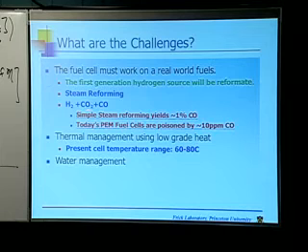You're supposed to only generate CO2, which is an issue in and of itself if you think that fuel cells are the answer to greenhouse gases. But you could think about things like you're going to do this in a big factory and you're going to collect the CO2 and stick it in California because you live in New Jersey or something like that. The real problem is you generate quite a bit of CO. In a typical one-step reforming reaction, you generate 1% CO in your output stream.